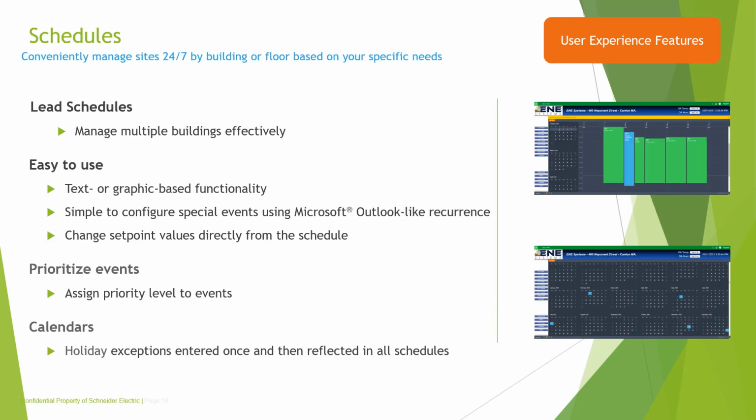Individual schedules can be assigned to shadow a lead schedule, allowing the user to change multiple schedules at once. An easy-to-read and manage graphical interface shown here in WebStation allows for quick editing. Events can be prioritized to override an existing schedule for a certain time period, avoiding a return to re-edit later. Calendars can be assigned to a schedule for holiday exceptions. Individual calendars can be created for multi-tenant occupancies.